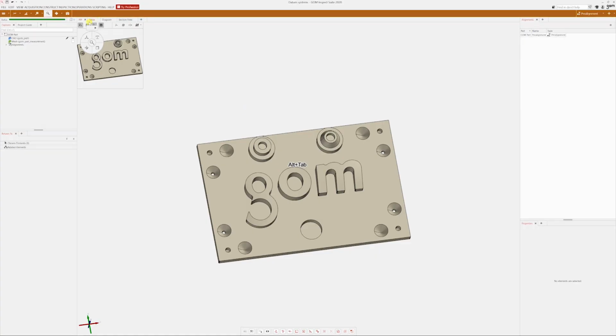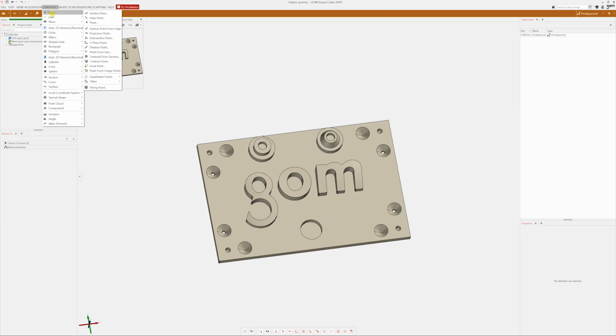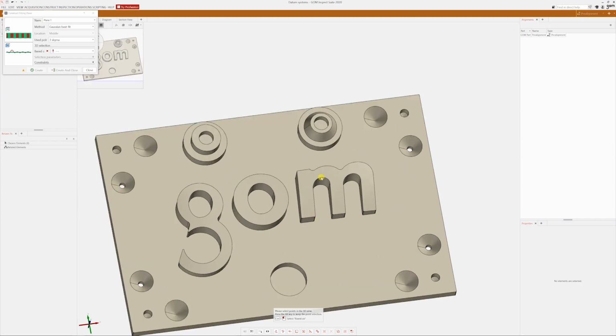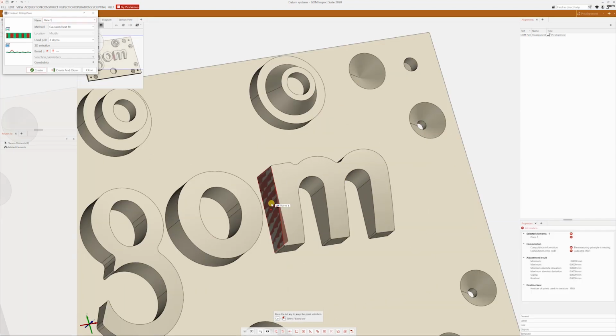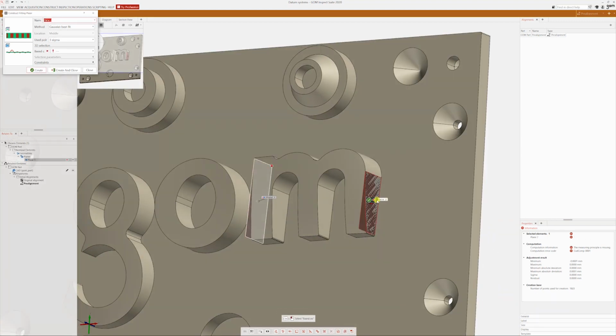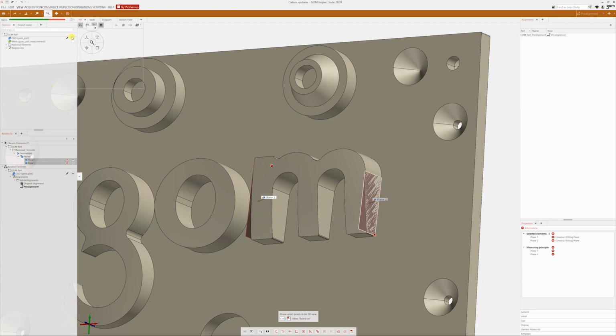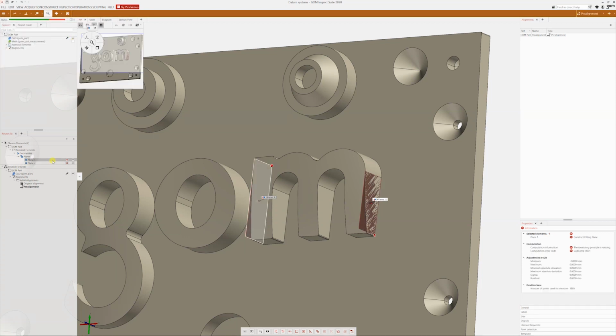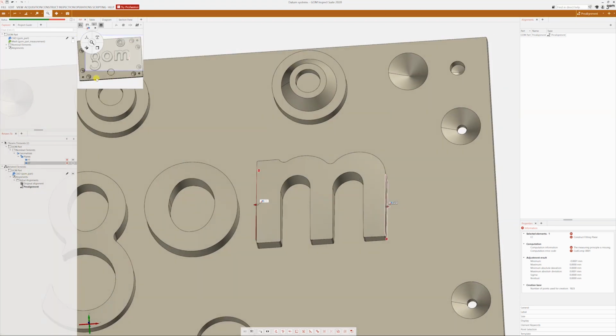So the way we do this is go to construction, plane, fitting plane, then we take a plane on the left side, and a plane on the right side. Okay, we rename them in order for us to work organized. We will rename plane 1 F1 and plane 2 F2, so we can know that they construct datum F.